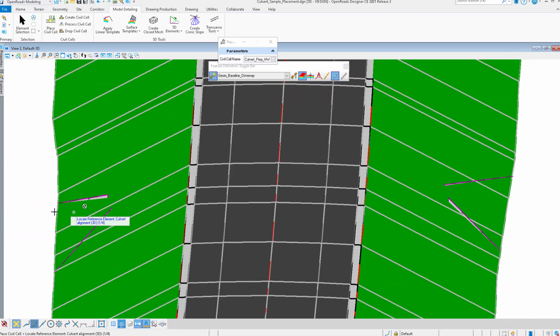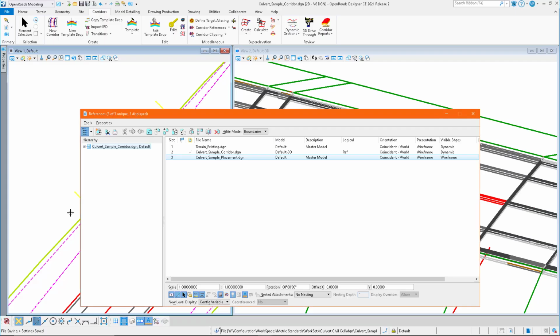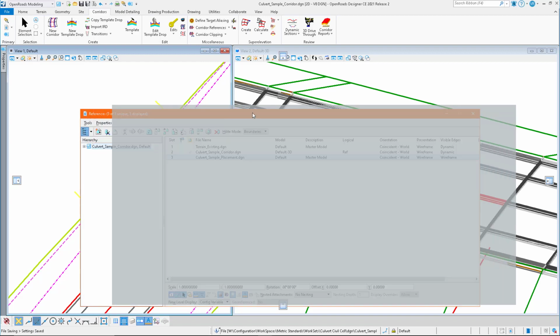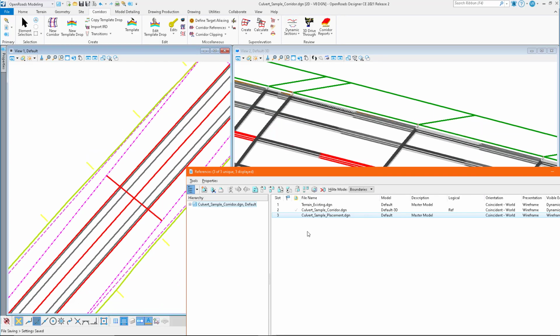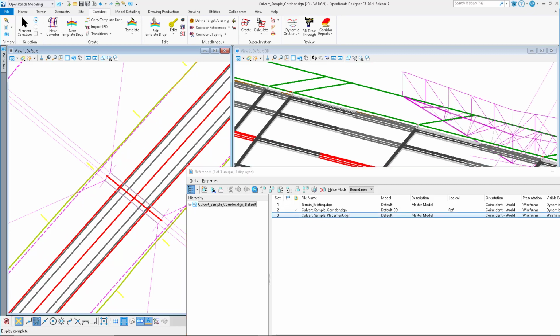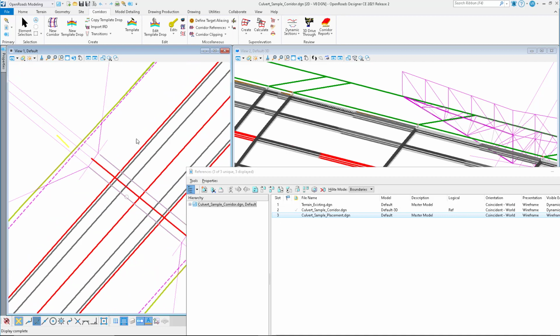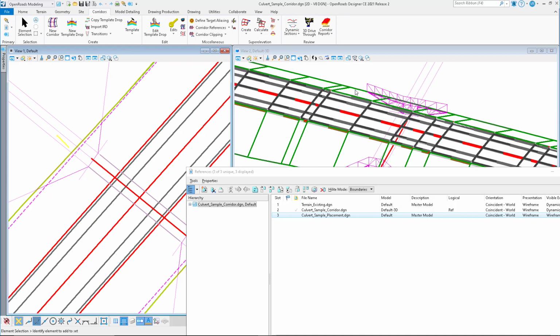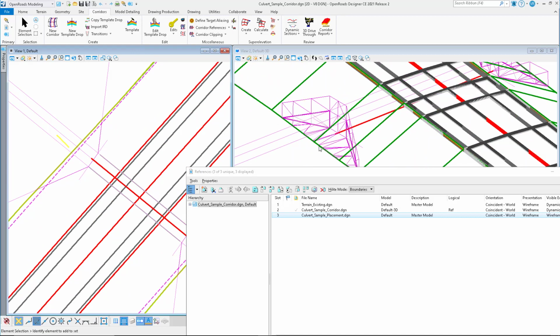And to see through this culvert, now we need to go back in the corridor file, and we reference the file in which we place the culvert. We just have to refresh it. Usually I just have the sign here, but it's maybe because I'm recording. So now I do see I have the culvert that is referenced, and I used these terrain models as targets to compute the side slope of the corridor against.